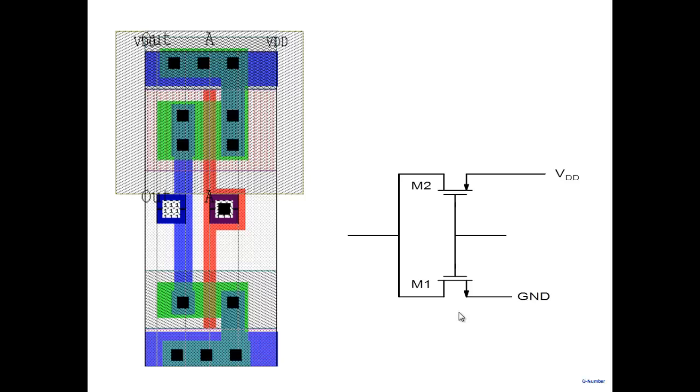Check if I'm calling this the ground terminal here, this is the VDD terminal here. So this one is ground, and this is the poly here. The same poly is running, so this poly is running here, another transistor here. This is connected to, let's say, VDD here. These two are shorted together. These ends, let's say this is the drain, the drain of one PMOS and the drain of the NMOS are shorted together. So this is what it is.